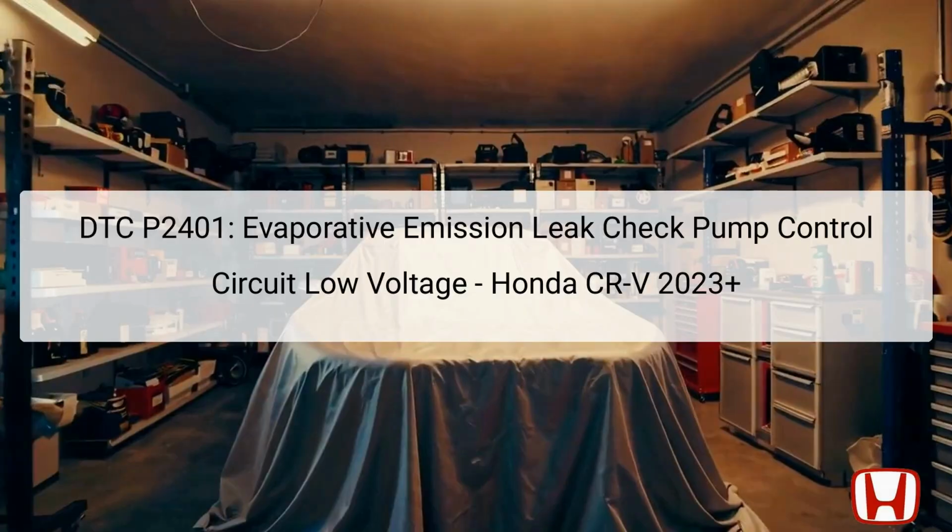DTC P2401 refers to an issue with the evaporative emission (EVAP) leak check pump control circuit in Honda CR-V models from 2023 onward. This diagnostic trouble code, specifically indicating low voltage in the control circuit, suggests that there's a malfunction with the EVAP leak check module's vacuum pump when the powertrain control module (PCM) sends an off signal.